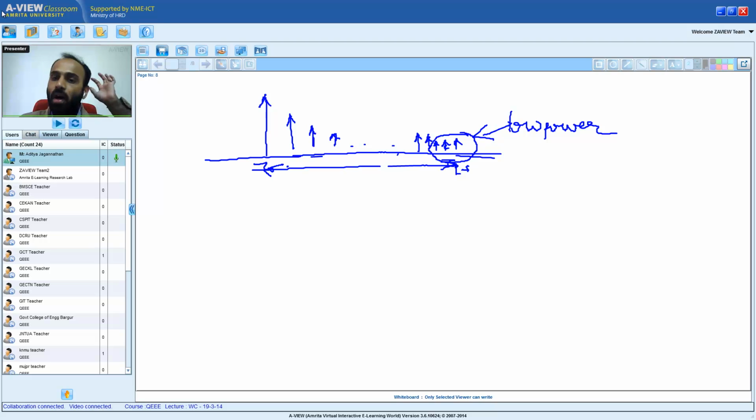So the power in the paths that arrive later might not be significant compared to the power in the paths that are arriving earlier. So these low power paths are not significant, they might not have significant power. Therefore, a correct measure of the delay spread will have to weigh the delay. I have to look at the weighted delay.